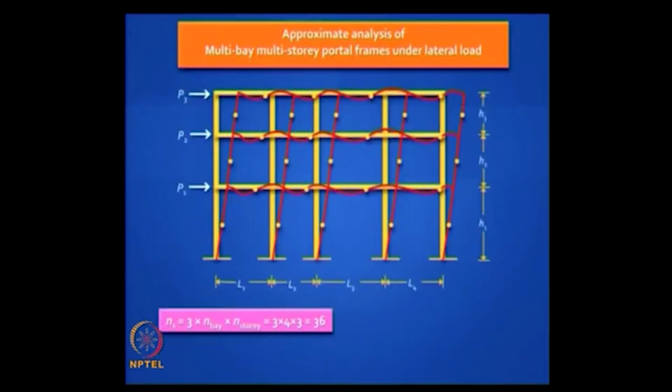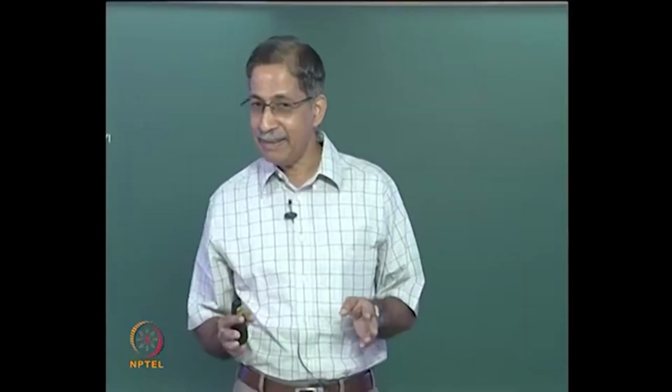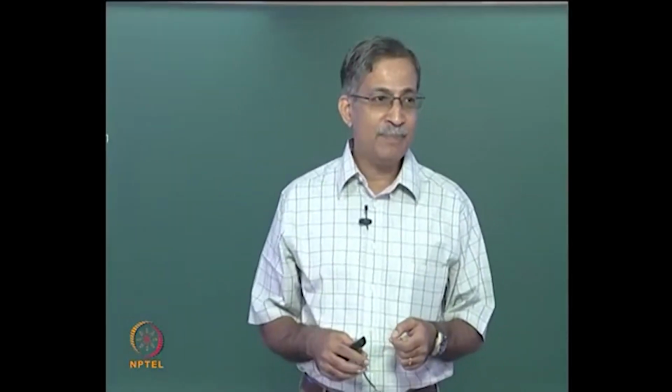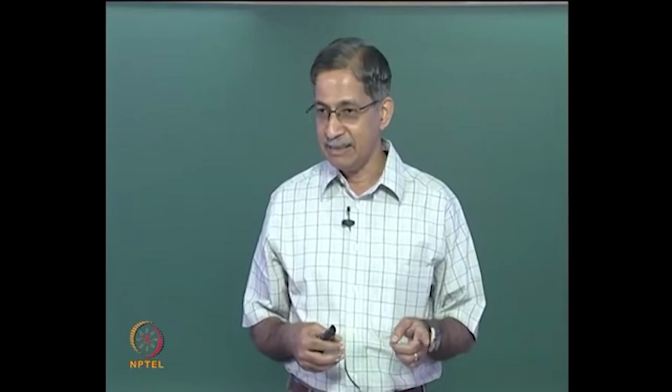Now let us take the more general problem of multi-story, multi-bay frames. Okay, and let us continue with the assumption that you have hinges, you have points of contraflexure in the middle of all the beams, which is not 100% true also, because it is not symmetric anymore, and in the mid heights of all the columns if the bottom is fixed. So these are big assumptions we make, but they are still not good enough to make the frame statically determinate.